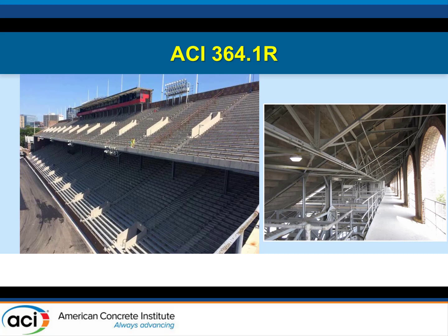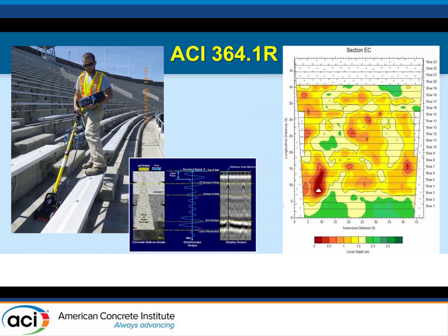The key thing, not only in evaluating a structure like this but as you go forward and want to do the repairs, is that you really want to get a sense of how much concrete you are really going to take out and repair. You can't just look at it from afar and come up with those quantities with any degree of confidence. So we did a couple of things here.